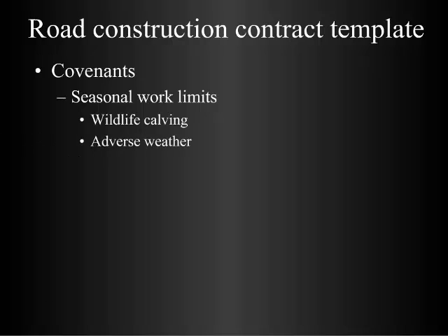Adverse weather, put in there that if the soils get saturated, you don't want them in there. You can't build good roads when the soils are saturated, so I'd definitely put that in, or also during spring breakup. Fire season restrictions, basically that would be on your burning. Have them burn in the winter, probably after the first snow, or however you want to put the restriction in there. So if you have snow on the adjacent trees, it can help them, give them a little bit of buffer, a little bit of moisture when the fire is burning.